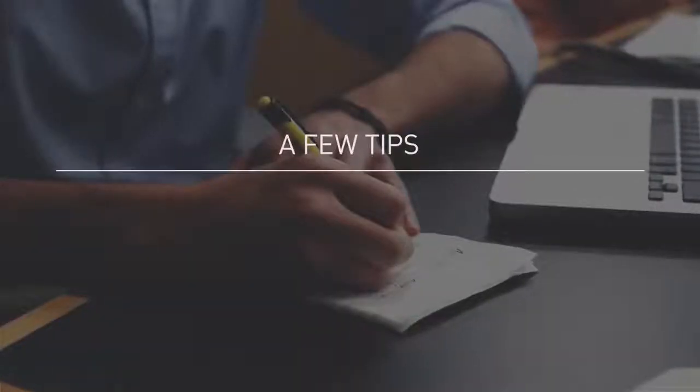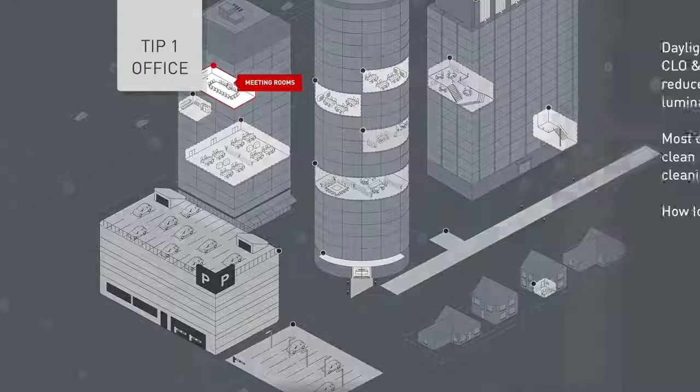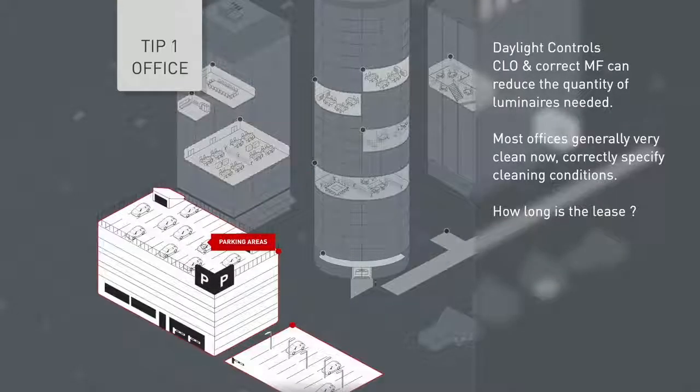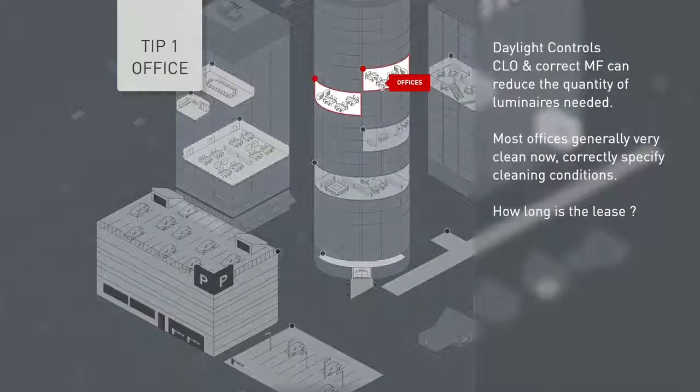Right, we'd just like to finish with a few tips, summarising what we've been talking about and hopefully trying to put it into context. So if we look at an office environment, some of the things you can do is incorporate daylight controls and incorporate constant lumen output, and by doing these you can affect your maintenance factor, which will reduce the quantity of luminaires you actually put in the space.